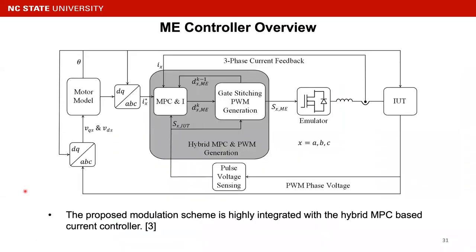Now let's look at the motor emulator controller. As we mentioned before, this is a hybrid model predictive controller, and the controller is running in the stationary frame. As we mentioned before, the hybrid controller is highly integrated with our newly proposed PWM strategy.